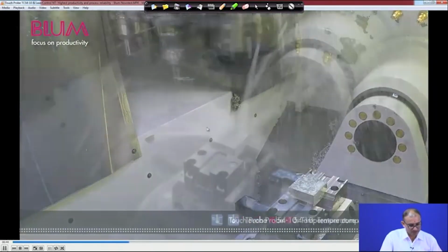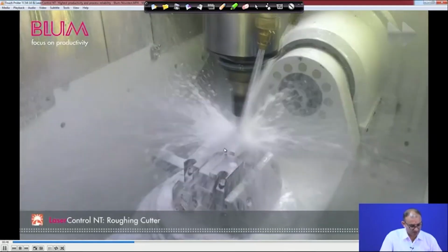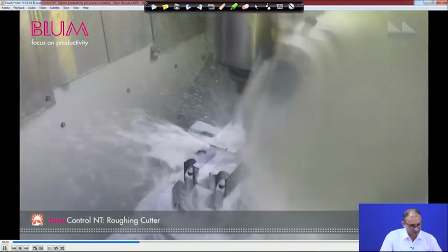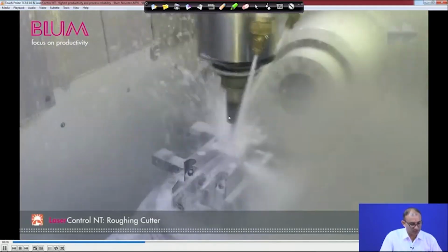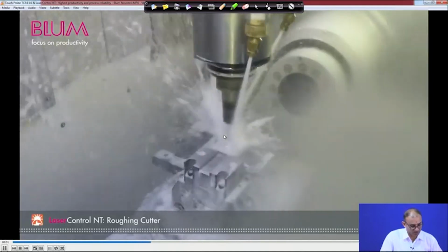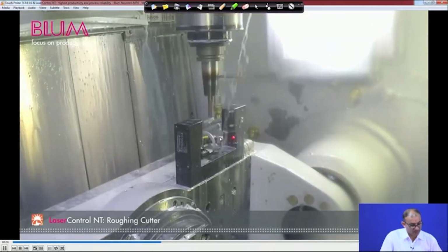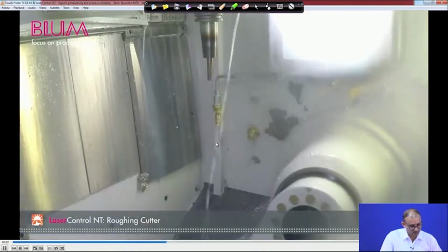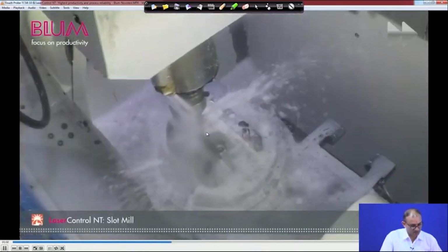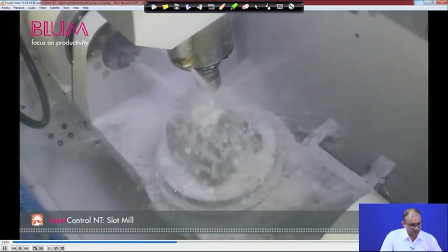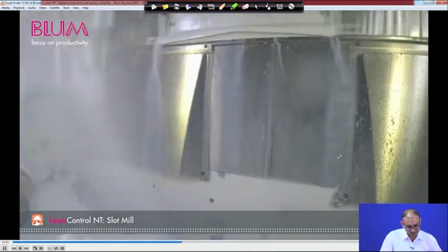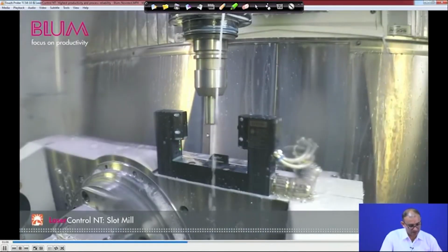So, once that part is over, then you do the machining operation here. After machining, what do you have to do? You have to measure the cutting tool, whether the tool is worn out or not. Right. So, this is that laser part again. You put the laser here and then you measure, it is still useful. Then do the second operation, slot milling. Then this system is available here, at that location. Now, again do the measurement here.